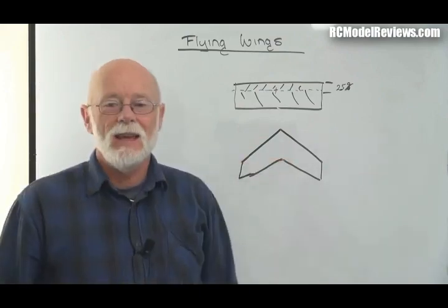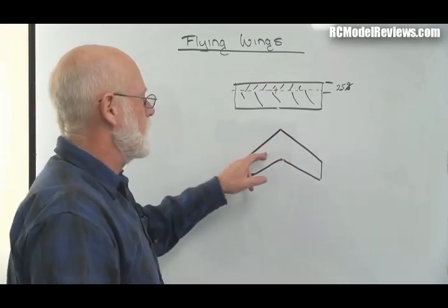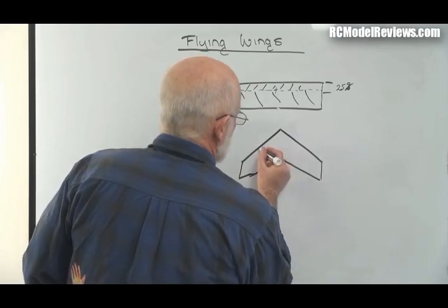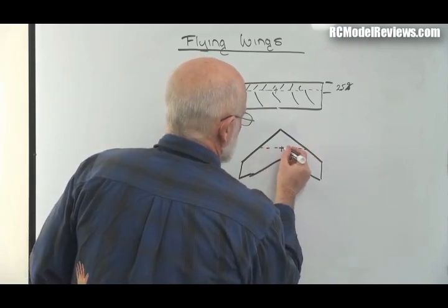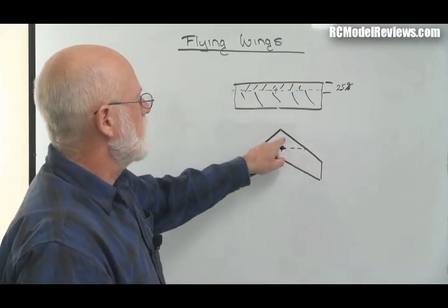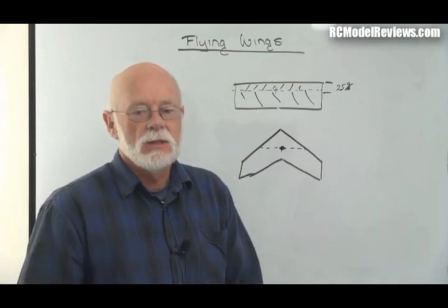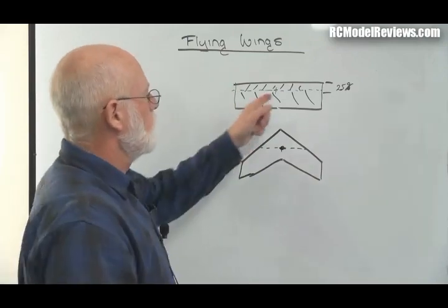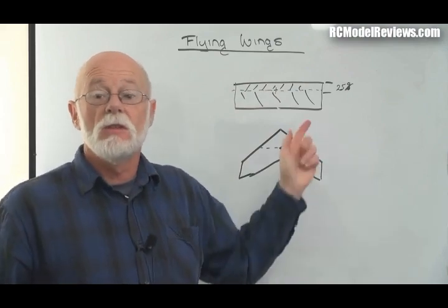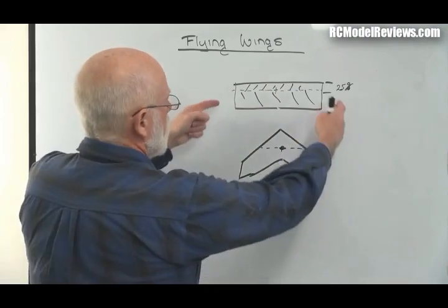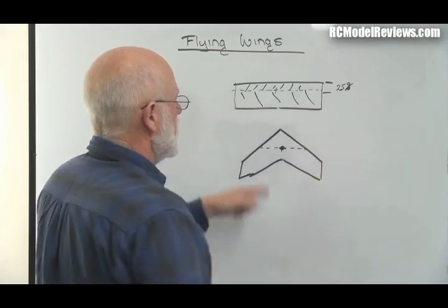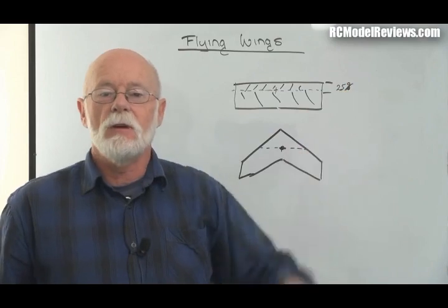On a swept wing, not so easy, right? So on a swept wing, you have to calculate the areas. And you'll find on a swept wing, if we draw it like this, the CG is probably about here, right? We've got 75% of the area behind the CG, 25% in front. Interesting thing happens here. Now, we need to get our CG forward. What can we use to move the CG forward? Because you'd think a wing will normally balance halfway, and this wing would balance probably way back here. So we need to get the CG forward using heavy items up the front.